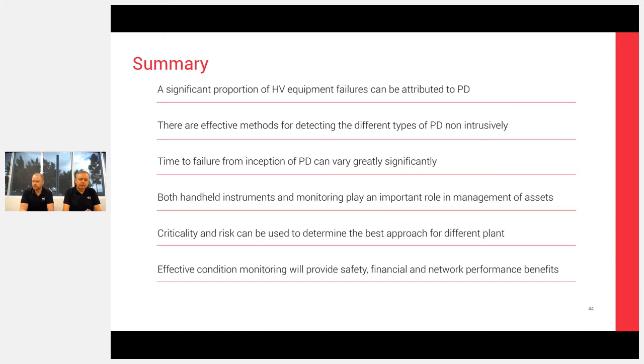So what we can do, because it's a relatively simple case to reposition due to the magnetic nature, we usually put one on an appropriate part of the switchgear depending on the type. So we make an assessment of the type of the switchgear, the construction. Sometimes we'll put two sensors, but generally it's one or one every other, and we'll see where signals will go. So that's how we'll make an assessment on the TEV, because it will transfer.